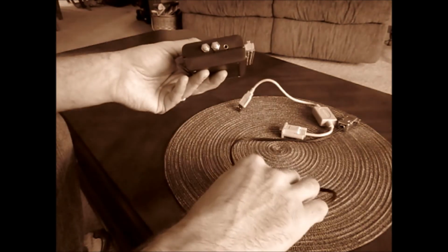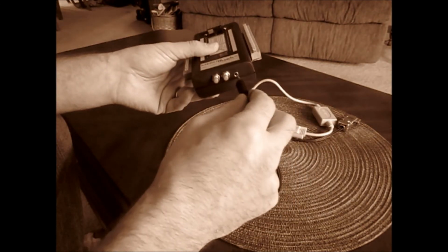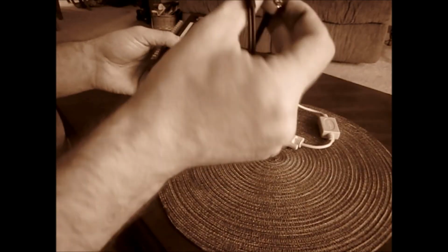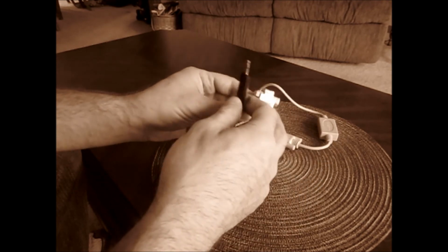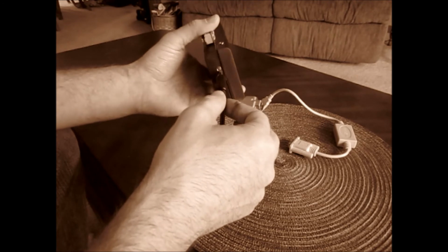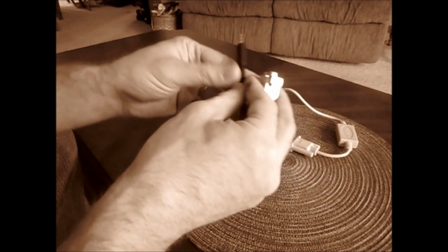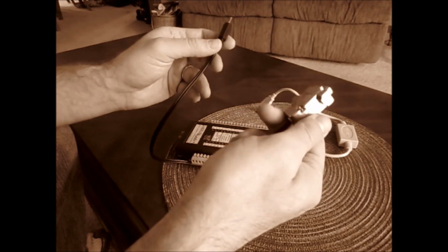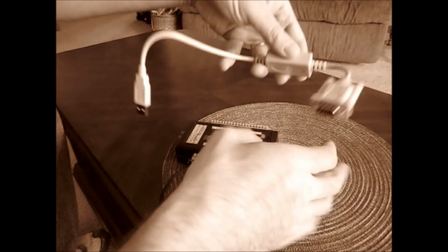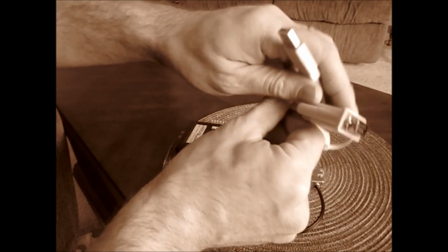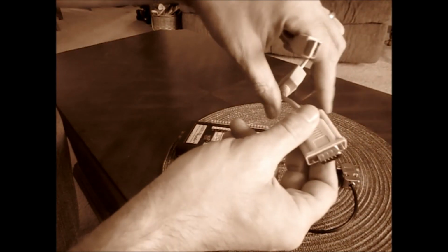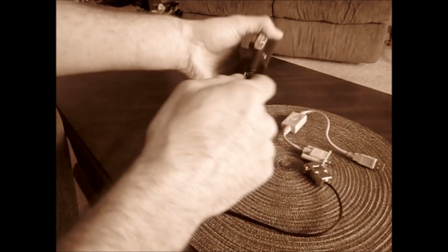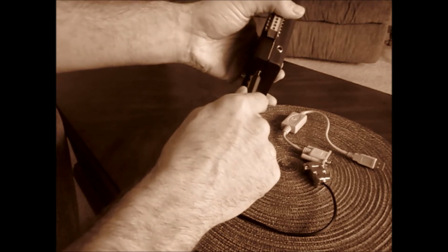This right here is the port for the RS-232, which communicates back and forth to the PC, and it comes with one of these little cables, a 9-pin serial to the RS-232 pin here. So if you don't have a 9-pin port on your PC, you're going to have to just go up to Best Buy or get one of these USB to 9-pin adapter ports and just plug one into the other. And then, of course, the USB goes into the PC, and this one gets snapped in here, and this gets snapped into the back of the MerlinMatch.